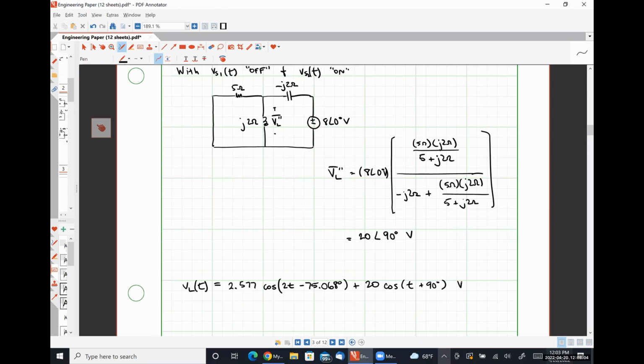What we are going to do slightly before we get into three-phase power is introduce the concept of filters. Filters are all about kind of what we did here, recognizing that the impedance of capacitors and inductors change as a function of frequency and exploiting those relationships to either pass or attenuate specific portions of signals.